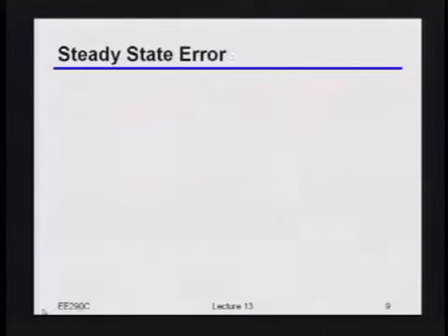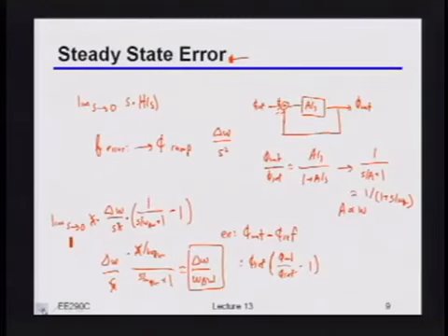Okay, so just to come back to here, we said that if we really did have this plesiochronous system with that CDR that I drew before, then we again had this bad situation where we have this trade-off between how fast we can track those ramps, and therefore how much static phase error we get, versus how much we can filter out the ISI jitter. Okay? So what do you guys think we're going to do? How are we going to fix this problem? We have the same problem in PLL, so put one more. Yeah, there we go. Exactly.